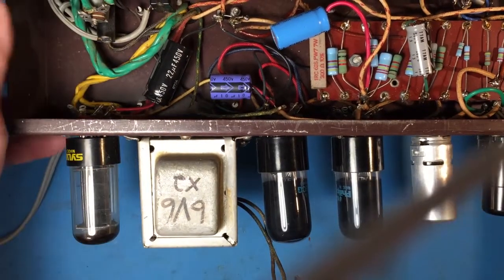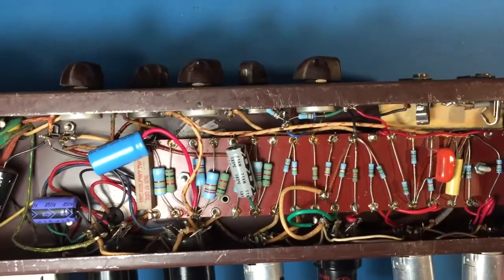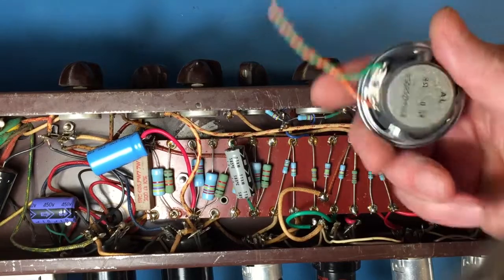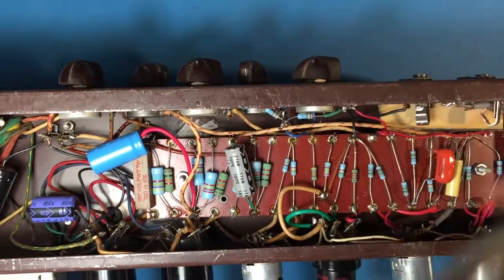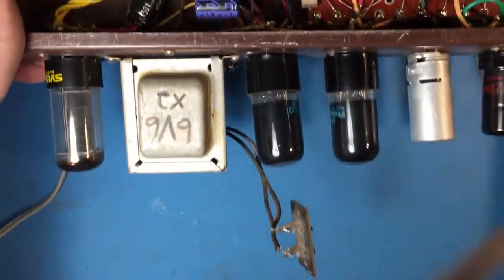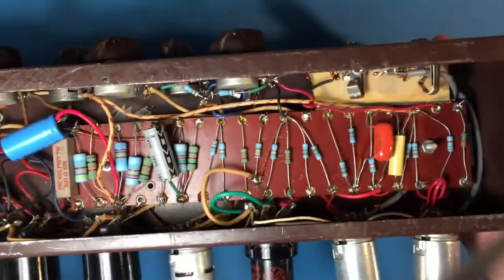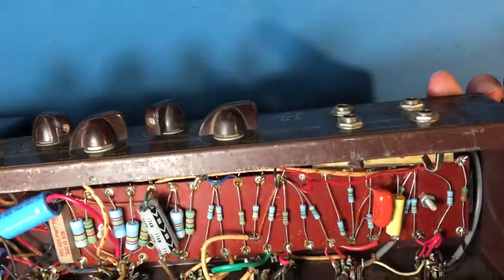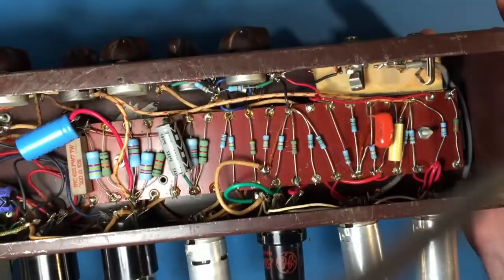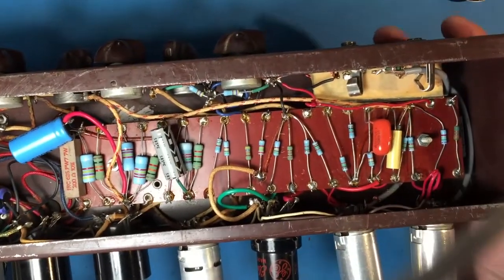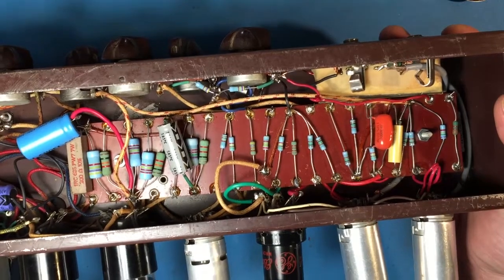And we don't know if our loudspeaker has the proper impedance, which is 8 ohms, to connect to the terminals on the back of the Gibson amplifier. And just by looking at this, I'd say that is a daunting, tall order to mathematically figure out how to make these 2 things work. So that's where things like Thevenin equivalence come in.